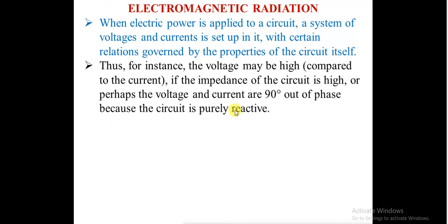So there is a phase difference between the voltage and current. If the circuit is reactive, it can be inductive or capacitive. The current lags the voltage by 90 degrees if the circuit is inductive, and the current leads the voltage if the circuit is capacitive. And there is no phase difference between the voltage and the current if the circuit is purely resistive.